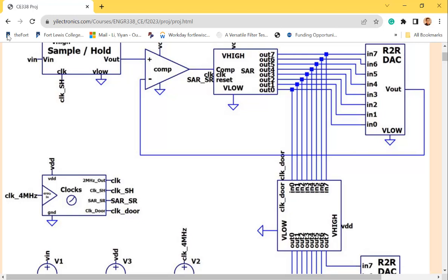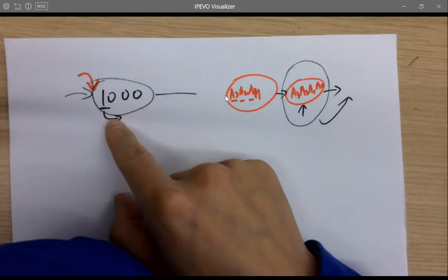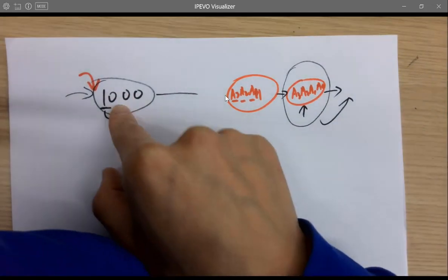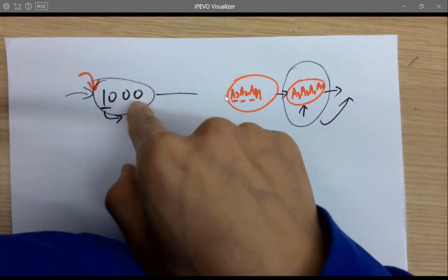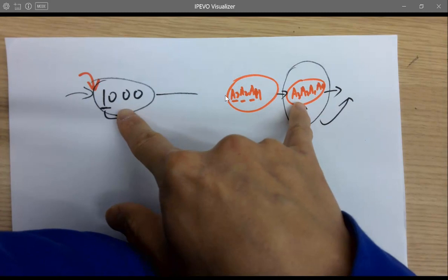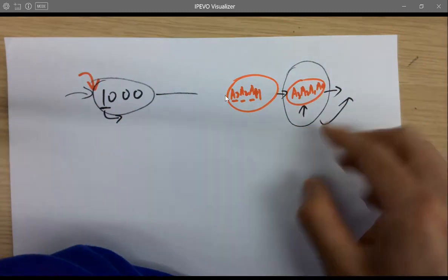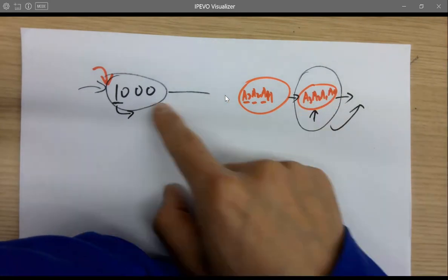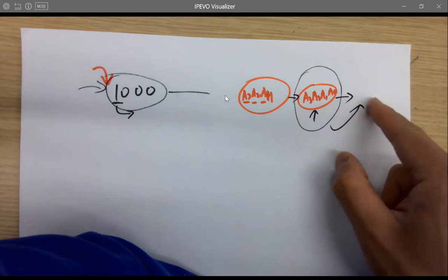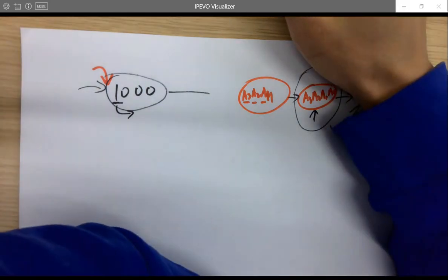So for the SAR logic, on paper, we know we run it, we reset it, and we run it for another 4 cycles. Counting the first one, we have 5 states, and the very last one will be the final result. On paper, it's okay. We just stop here. What about in the digital circuit? What if it keeps doing this comparison and keeps running? What's going to happen based on the physical circuit here?